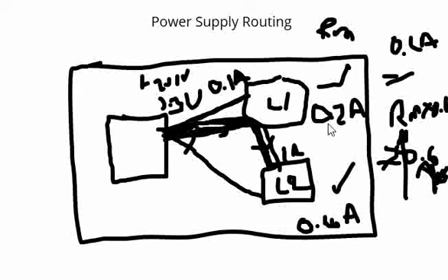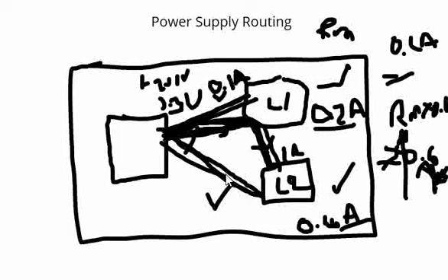Now in this case, we can have a thicker trace, and we can have another trace, and the current of 0.2 amps, as we talked initially, will flow through this. The current of 0.4 amps will flow through this, and if we assume that the trace resistance is Rm of each, then the voltage drop because of this trace will be much lesser comparatively, right?